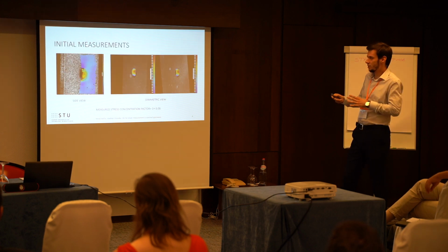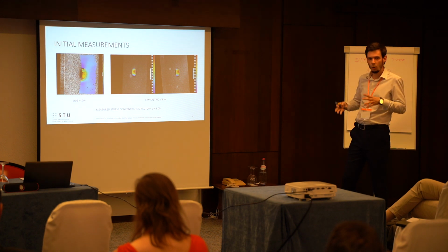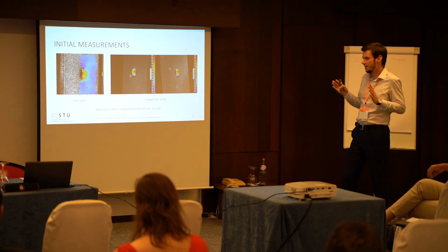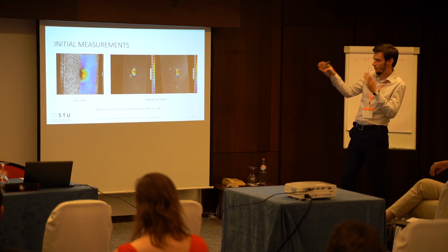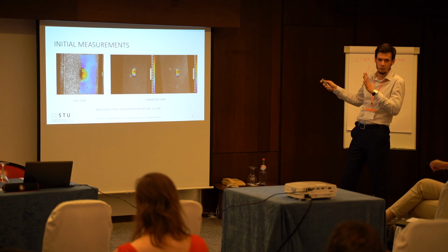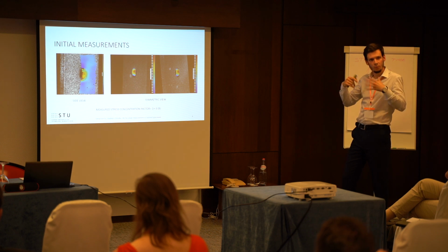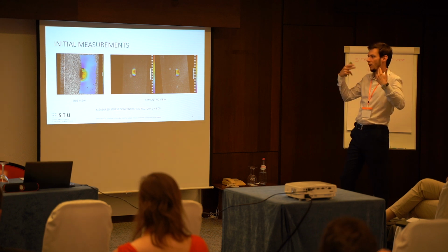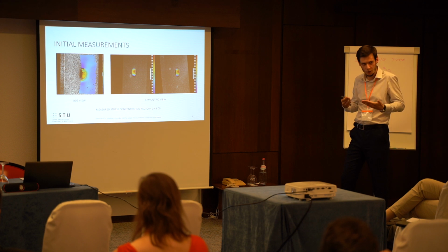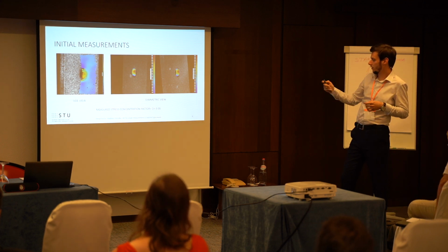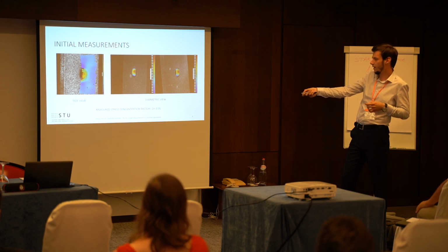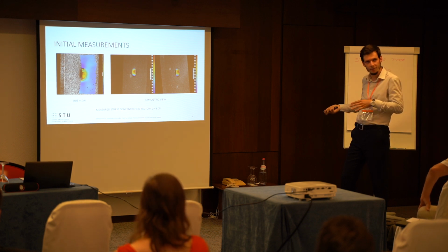First of all, we start with some easy examples, and that's the open hole tensile test. We had two configurations. The first was a side view, and the second is the so-called symmetric view. The side view is quite useful, but the problem was that the hole has to be relatively large to get an appropriate result. We got results around 3 to 3.05.